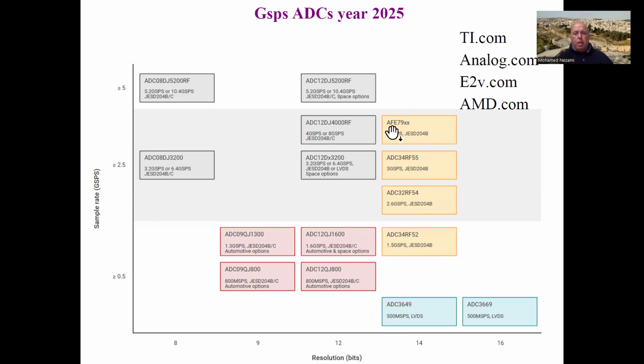And then the integrated front end, which has an ADC and DAC, they utilize AFE on there. Okay, so you can see that we're somewhere between 12 and, or maybe from 10 to 14 bits. This is where we're really going to be trying to be.